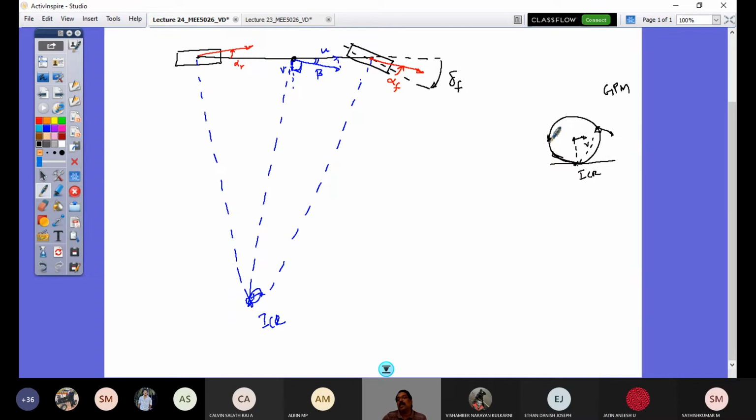So if I take this point, then what is the velocity? How do I get? I should join this to this point and draw perpendicular to that. So like that, in a rigid body, if I take any point, at that point velocity as it is rotating and translating, at that time what is that center is called an ICR. So you join all the points to that, and then you'll be able to draw the velocity vector.